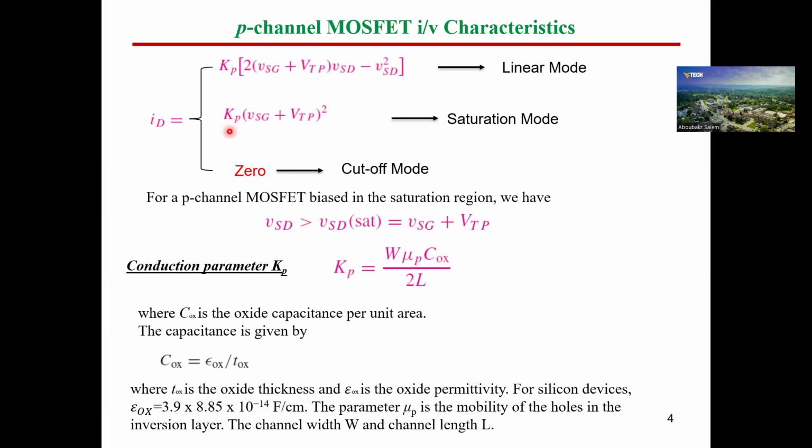And the same for the saturation. So VSG instead of VGS, by the way. Okay, so VGS is positive in the case of N-type MOSFET or N-channel MOSFET, and VSG is positive in the case of P-channel MOSFET. So this is a difference now. Because we reversed the letters, the sign will be positive all of the time. So VSG is for sure opposite to VGS.